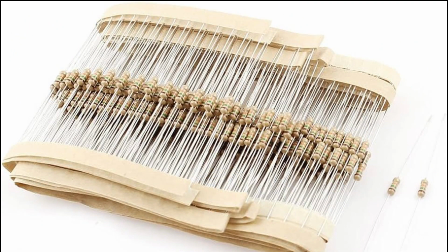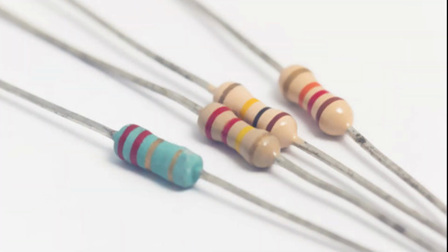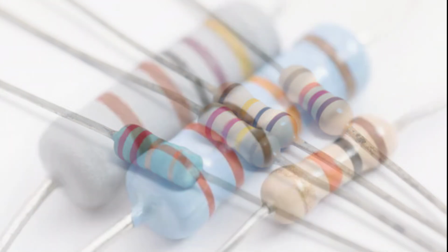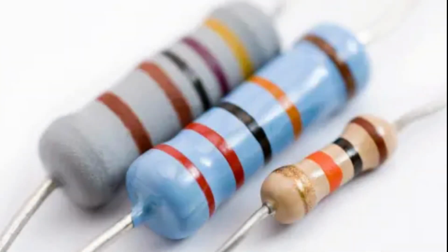Carbon resistors are the most common type of composition resistors. Carbon resistors are a cheap, general-purpose resistor used in electrical and electronic circuits. Their resistive element is manufactured from a mixture of finely ground carbon dust or graphite, similar to pencil lead, and a non-conducting ceramic clay powder to bind it all together.